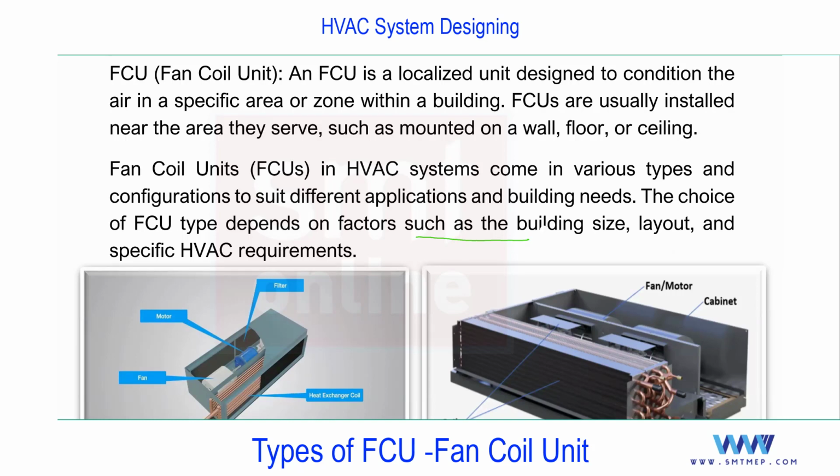And most commonly, the FCU is chosen as per the interior or architectural requirement, because finally the client is looking for a good interior. So most of the time the selection or the type of FCU is done by the interior, and they ask you to follow a particular type that suits the interior requirement. In actual practice, you'll get this information from the architect or from the interior.